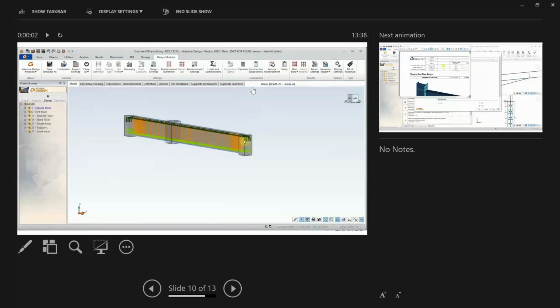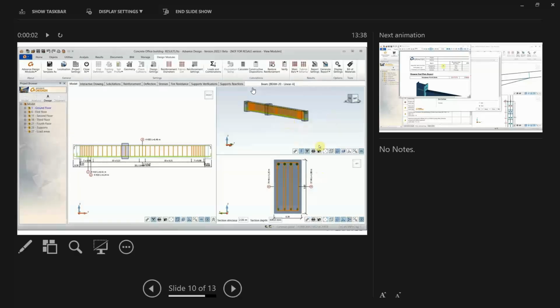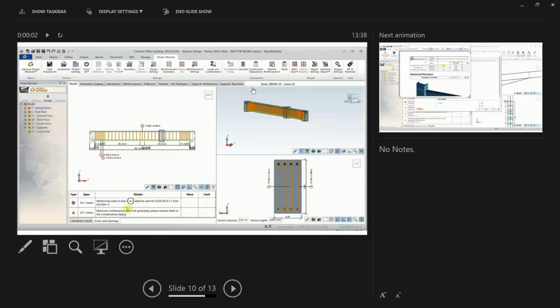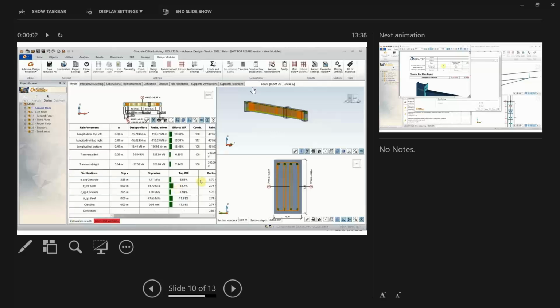You can take it even further, where we have a link with Revit as well. We can export the theoretical required reinforcement back into Revit, and in Revit, the detailer, the draftsman can modify the individual reinforcement. So there are 2 things I need to work on here: ductility class, and generating a new mark combination.